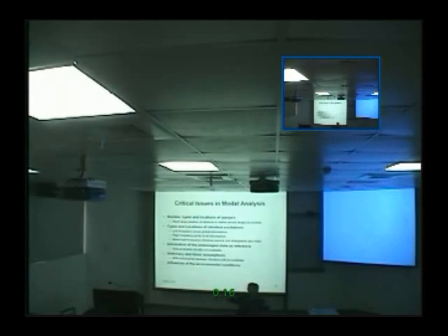If you want to define the shape of the bridge, how many sensors do you have to put in? One sensor? Of course not. One sensor you can only define one point. If you want to define the whole bridge, perhaps you need hundreds. But most people don't have hundreds of sensors, because each sensor that is sensitive for bridge damage detection will have to measure the bridge frequency down to about half hertz. Vibration to half hertz.